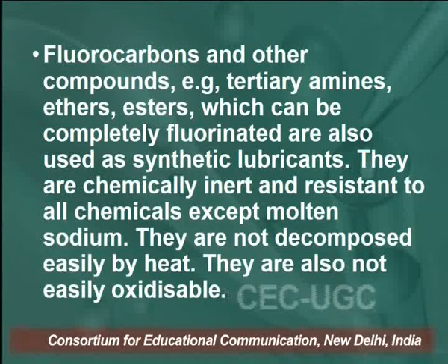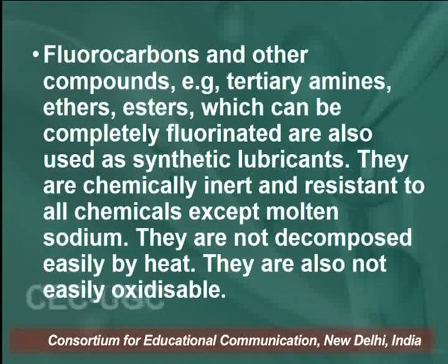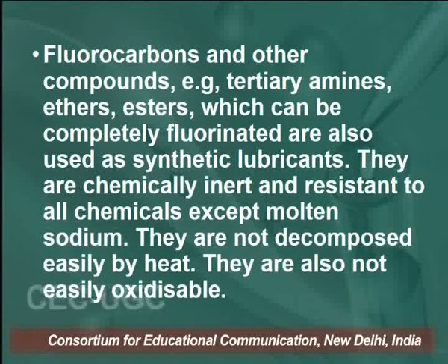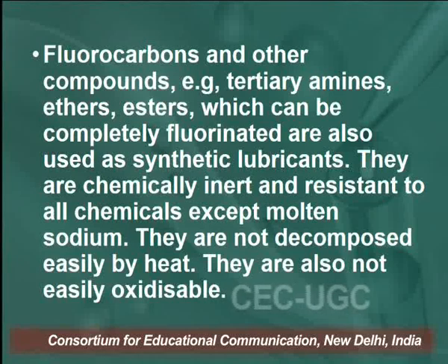Fluorocarbons and other compounds, for example, tertiary amines, ethers, esters, which can be completely fluorinated, are also used as synthetic lubricants. They are chemically inert and resistant to all chemicals except molten sodium. They are not decomposed easily by heat. They are also not easily oxidizable.